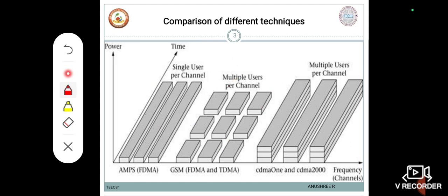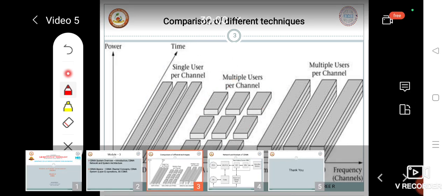So as we look into this, in FDMA, the user confines the transmitted signal power within this channel, and selective filters are used at both ends of the radio link to distinguish transmissions that are occurring simultaneously on many different channels. The frequency allocations can only be reused at a distance far enough away that the resulting interference is negligible.